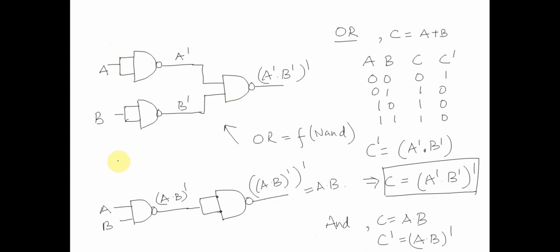And we said all the basic gates are AND gate, NOT gate, and OR gate, which means that any Boolean expression could be realized using these three gates. And we have made these gates from the NAND gate itself. So that gives us the indication that all Boolean expressions could be solved using the NAND gate itself. Thank you.